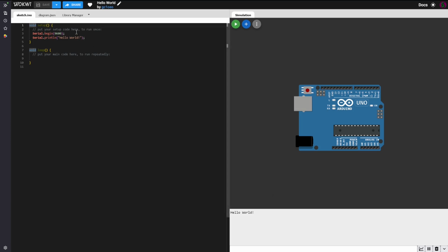We're going to put this in the serial monitor, so we have to first start the serial monitor at a certain baud rate. All of this will get explained in future videos. We're doing a print line. You'll notice the object-oriented nature of this. Hello world. So if everything goes well, hello world. There we go. I'm doing this in Wokwi simulator, obviously.